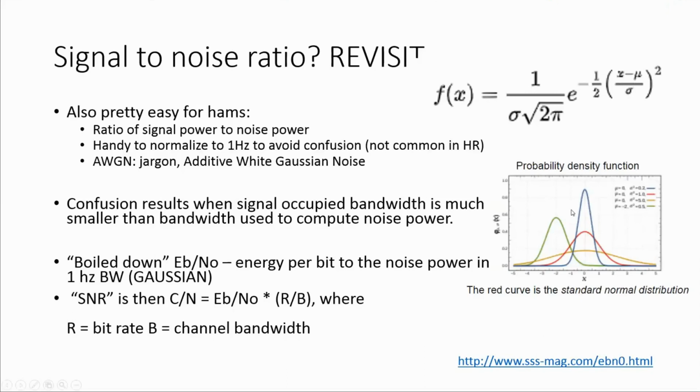So this is just an exponential function that's symmetric around the origin, and it's characterized by 2 variables, the mean and the standard deviation. The actual random value, the thing that's changing, is this x. So when you say noise expressed as this f of x, the x is the random variable. The random variable is a fairly complex concept, but in terms of noise, it's just if you have a trial where you pick a value, it's one of these values, and the probability of that value is this.